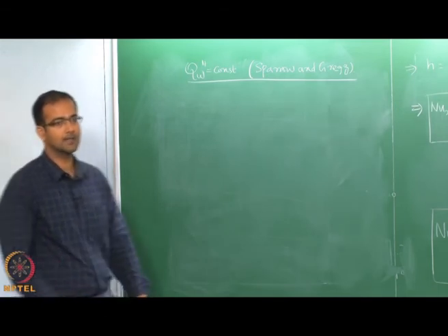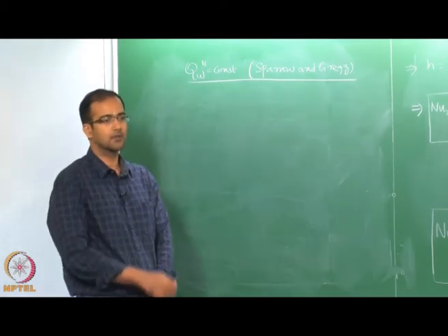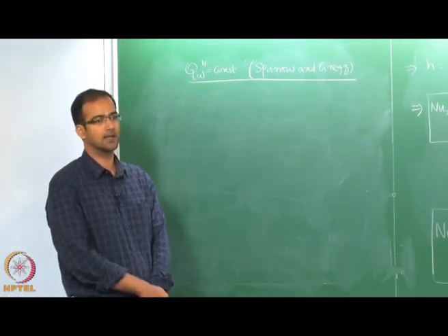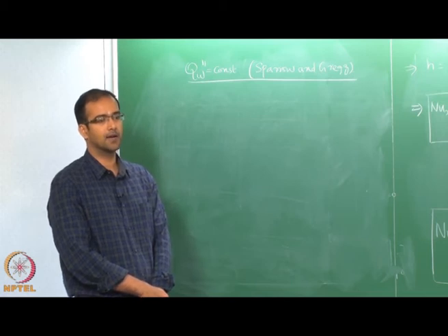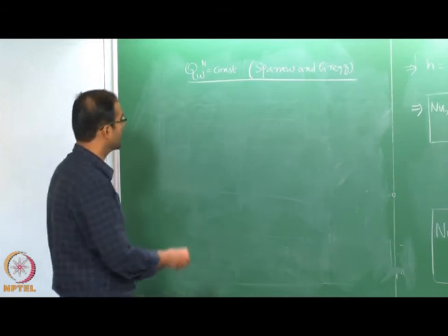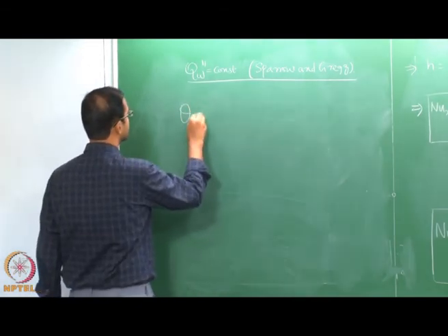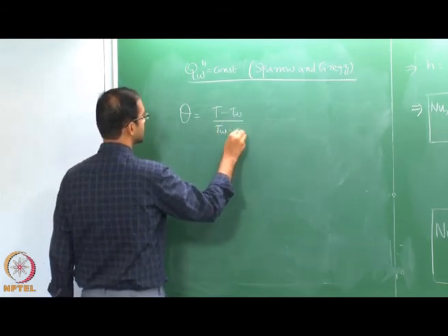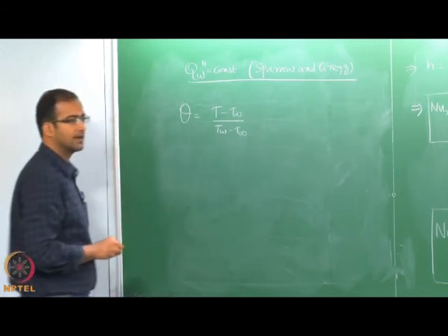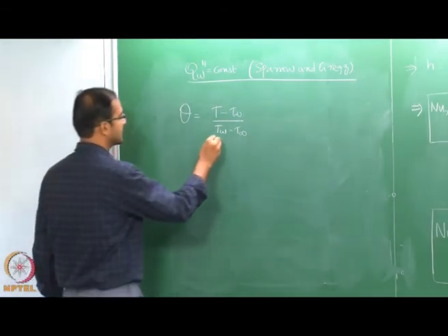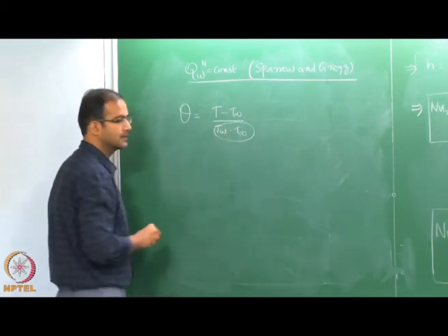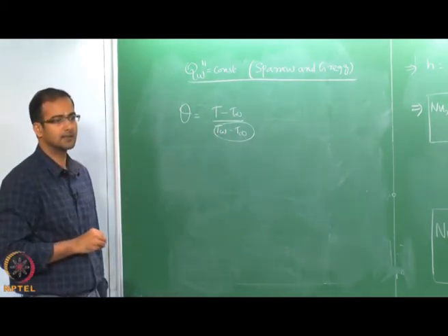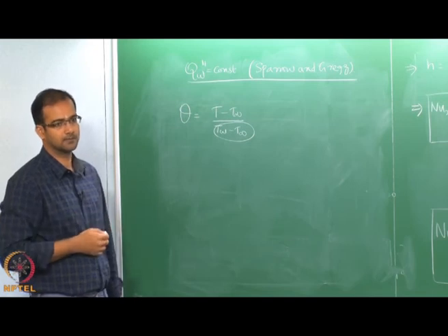Okay. So, now similar to the flat plate case where we had constant heat flux boundary condition, now we have to find another similarity variable. We use the same similarity variable more or less there, but the way we have defined our non-dimensional temperature theta. Okay. So, in the constant wall temperature case, we use this definition, and in the constant heat flux case, since T wall minus T infinity is not a constant, we have to replace this in terms of heat flux, which is known, which is fixed.